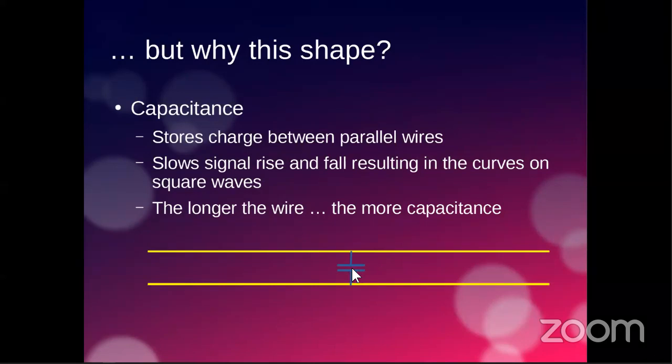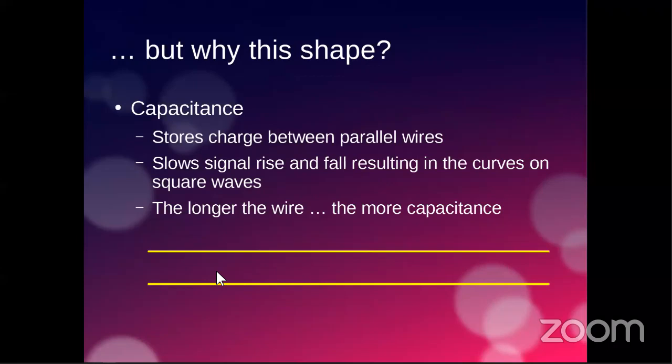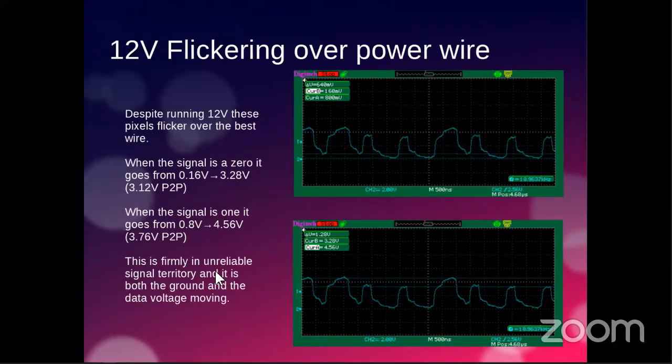So yeah, it's a logical capacitor there. So you definitely don't want to be trying to fix your signals by adding capacitance. That ain't going to help. The other thing that you can get is inductance across the wires as well, and that can lead to things like impedance mismatches, which can lead to signal reflection. We'll come back to that.